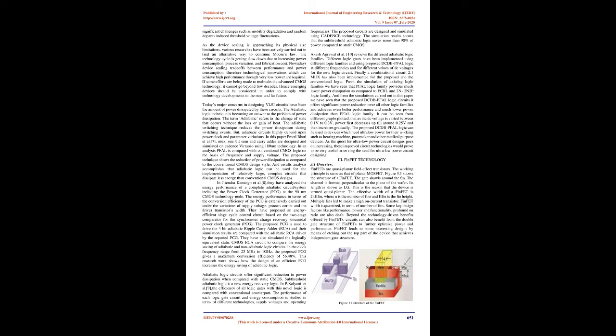For the first time, they have proposed a novel bottom spacer fin-shaped field effect transistor, FinFET, structure for logic applications suitable for system-on-chip, SoC, requirements. The proposed device achieved improved short channel, power delay, and self-heating performance compared with standard silicon-on-insulator FinFETs. Process aspects of the proposed device are also discussed in Mayank Srivastava et al. [5]. Physical insight into the improvement toward the short channel performance and power dissipation is given through a detailed 3D device/mixed mode simulation. The self-heating behavior of the proposed device is compared with standard FinFETs by using detailed electrothermal simulations. The proposed device requires an extra process step but enables smaller electrical width for self-loaded circuits and is an excellent option for SoC applications.